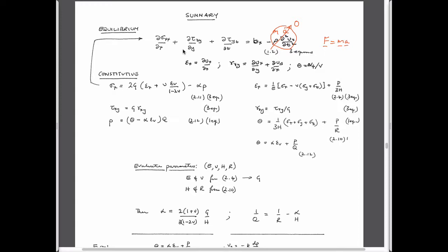Heat fluxes are proportional to gradients of temperatures. So conservation equation, continuity equation where dependent variables remain continuous, constitutive equation that links two variables, stresses and strains, fluid pressures and fluxes, and then finally boundary conditions and initial conditions. So that's the path for a normal solution.